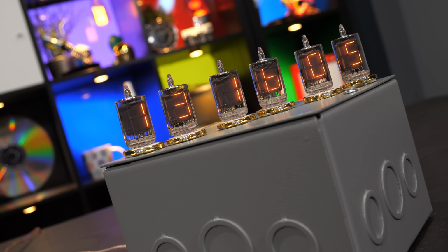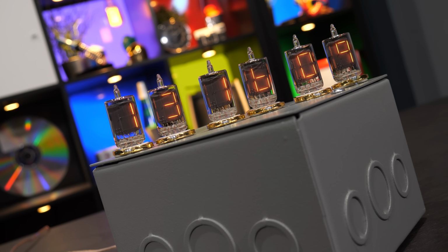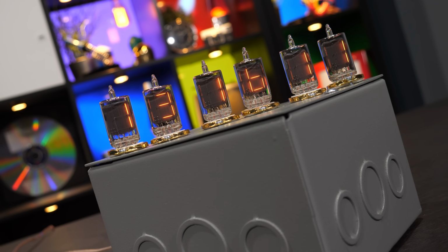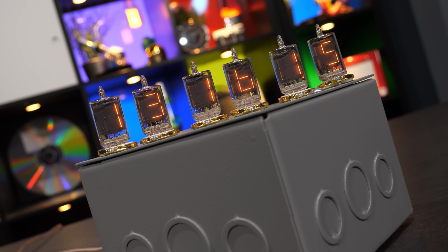The ridiculous simplicity of these meant that you could drive them directly from a 7-segment BCD decoder chip, all powered by the same 5-volt supply as the rest of your newfangled digital widget. That would save money in the hardware design, and since the Numitron itself is so freaking simple, the display tubes were cheaper than the competition. So it wasn't a terrible idea.